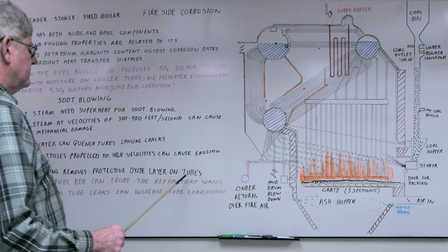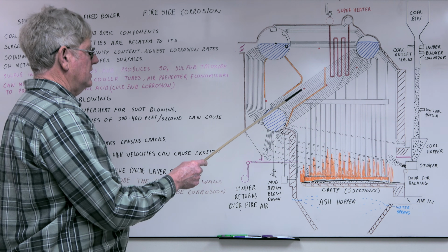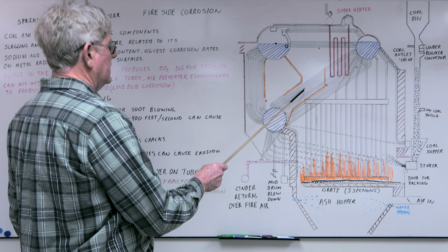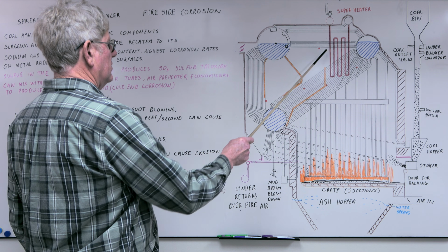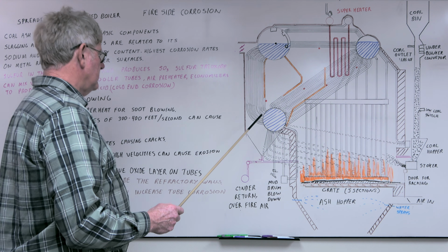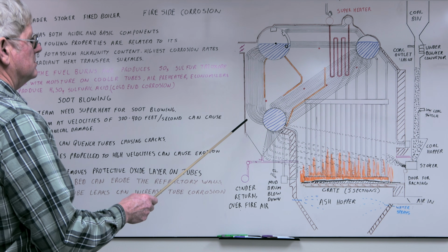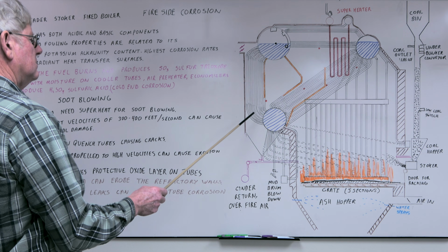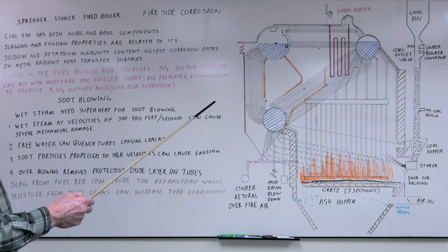It's not too common. This type of boiler had a manual soot blower. A chain came down to the floor and you'd pull it. Then as you rotate the soot blower, it'd open up the steam valve. It'd blow steam as it slowly rotated around, then it'd come back around and shut the steam valve. So as a mechanical operation, you'd blow the steam once or twice a shift. Newer pulverized coal units have automatic soot blowing. They can overblow at low loads, but usually it's not an issue. Something to be aware of is that too much soot blowing can cause you problems.